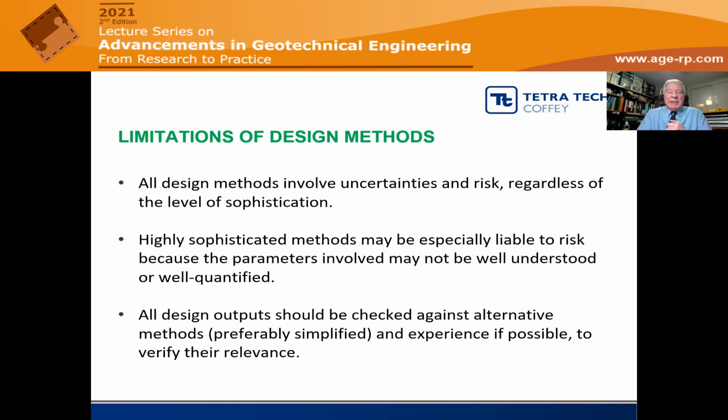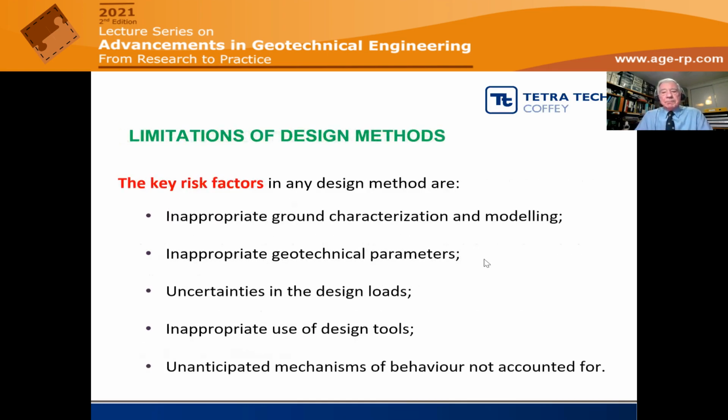And the other thing that I feel very strongly about, and if there's one message that I leave you with, it's this: if you are using sophisticated methods, please check them against simpler alternative methods to make sure that you're getting a sensible answer. Because if somebody comes up to you and says, I've done a calculation and we have 10 kilopascals and it's going to settle 2 meters, I think you would have to question whether that calculation is valid, because it doesn't fit with simple methods and it doesn't fit with experience.